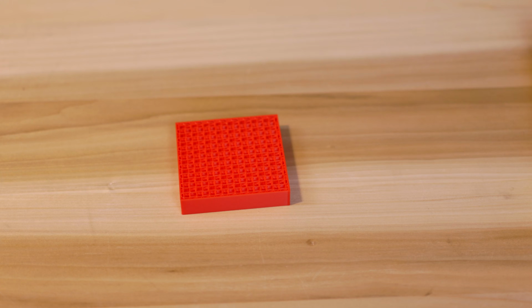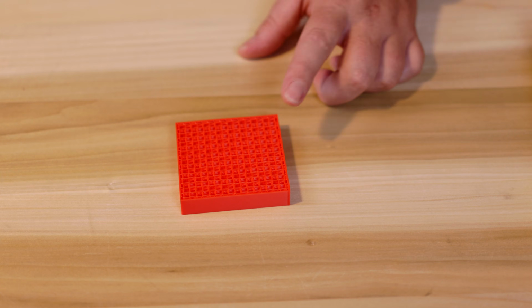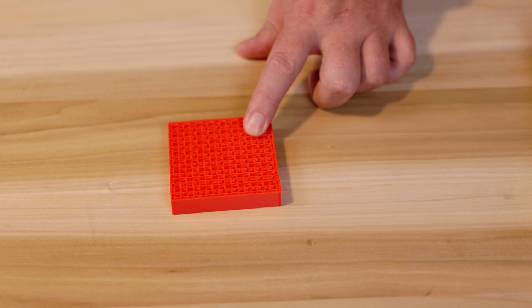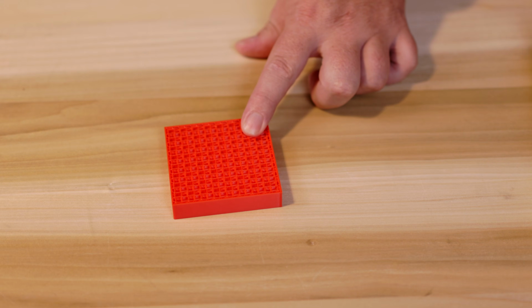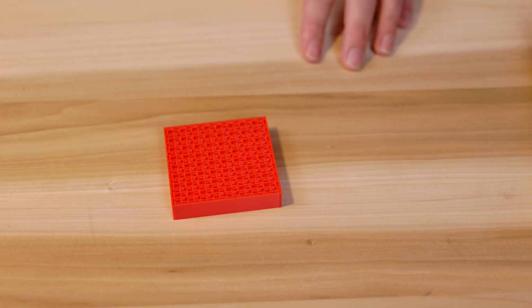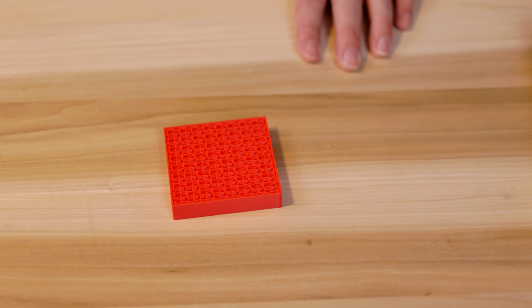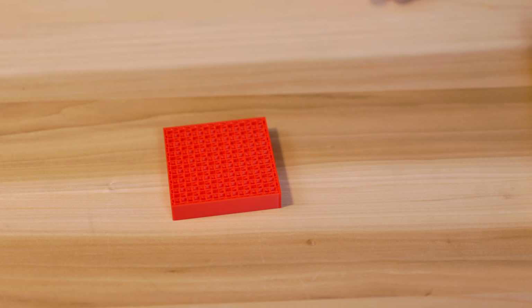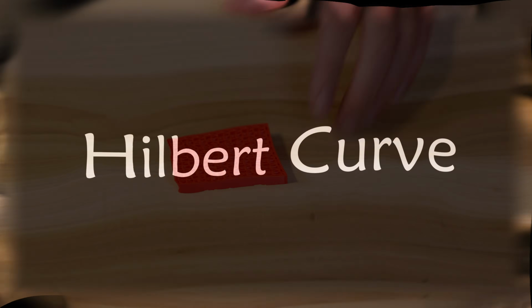Next is 3D Honeycomb, and this is a three-dimensional evolution of the honeycomb pattern. Use case, objects requiring strength in all three dimensions. The pro here is multi-dimensional strength. The con is it does take longer to print as it is the longest one on the list. Ensure nozzle is properly calibrated to handle intricate patterns, and that's the printing tip there. Print time on this one was 2 hours and it used 72.67 grams.